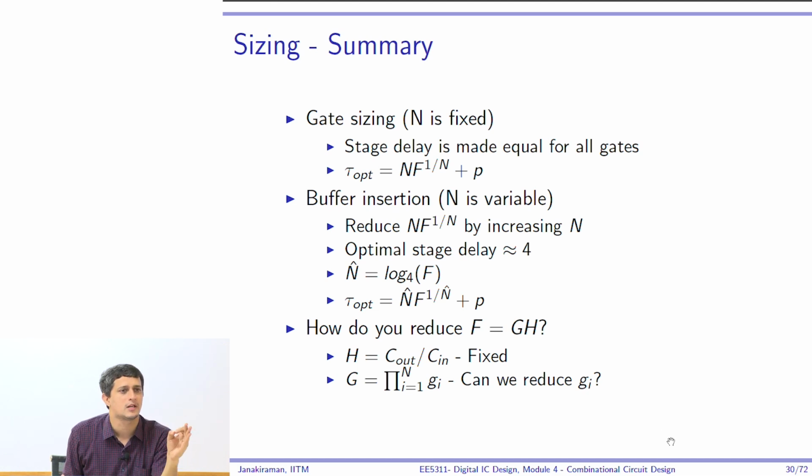which will simply translate to the gate logical effort Gk. In order to reduce the delay of a path any further, I need to reduce the logical effort of the gate. The remaining part of this module will be a discussion of various styles of CMOS gates where I simply reduce the logical effort significantly step by step.